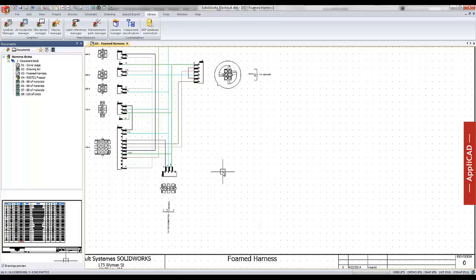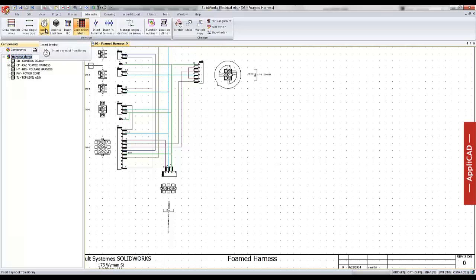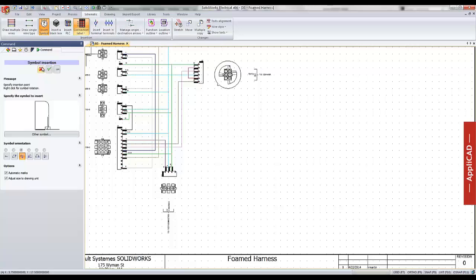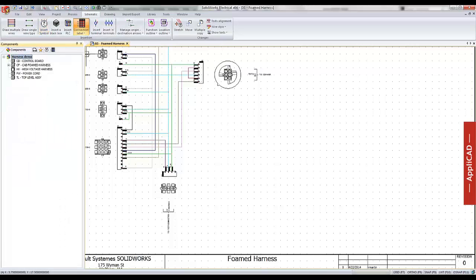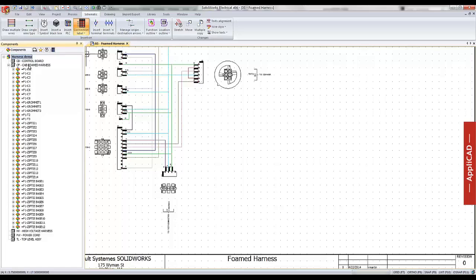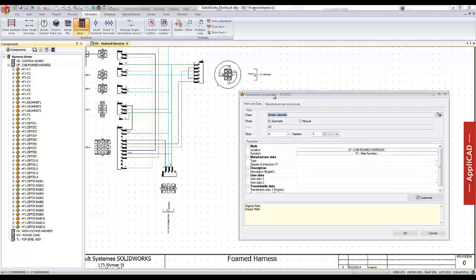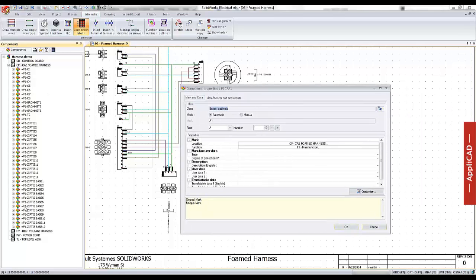So now that we defined that in our library, let's go ahead and use it. You can either add a symbol and start designing that way, or if you know what your parts are ahead of time and build it up like a kit, you can do that too. You can go in by adding components to your component navigator without placing anything on the page. Similarly, another way is the mechanical engineer can add things into the 3D space, and they will appear in this navigator as well because he has the same navigator in SolidWorks.